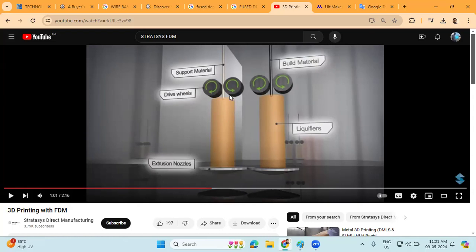To understand the pinch roller mechanism's function, it is essential to know how it works. The pinch roller is responsible for guiding the filament into the liquefier where it is melted and finally extruded. The filament moves through the pinch roller and into the liquefier through a small orifice.